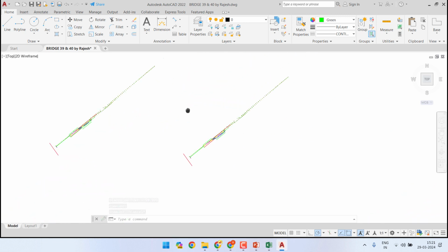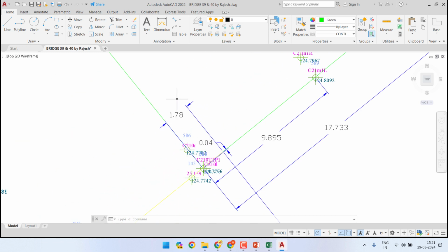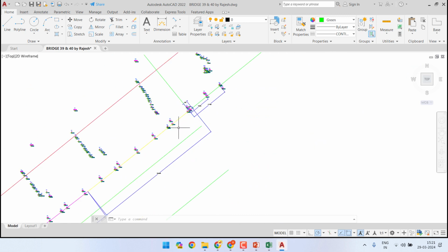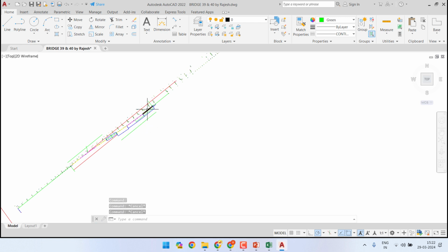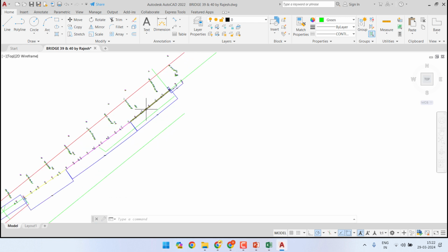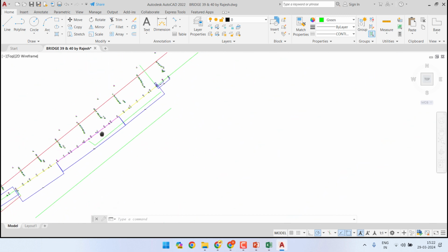And when we used the transition length as 60 meters, overall length of the curve was approximately 3 to 3.5 meters more than 210 meters, that is, we can say 213 or 214 meters. The advantage we have is that our length of transition has increased to 60 meters. Also, for the purpose of speed relaxation, we need higher length of transition, and that is what we are getting here. So this solution is more desirable provided our OHE parameters are more correct.